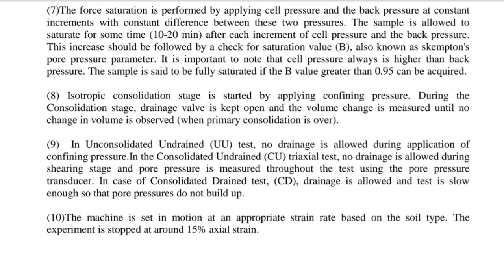8. The isotropic consolidation stage is started by applying confining pressure. During the consolidation stage, the drain valve is kept open and the volume change is measured until no change in volume is observed, when primary consolidation is over.